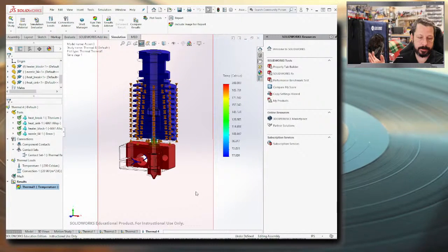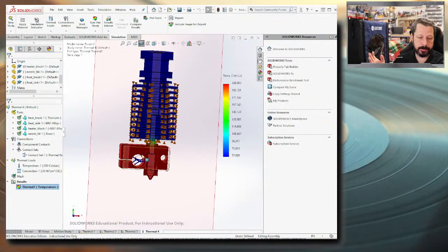You have different combinations where this heater on a volcano, for instance, a volcano hot end, is aligned vertically with the nozzle to try and get more heat right up against the nozzle. And so obviously that makes the heat break longer. So you lose a little bit of Z printing height by using a volcano hot end, but you gain more heat being put into the filament right beside it, vertically beside it, aligned with it.